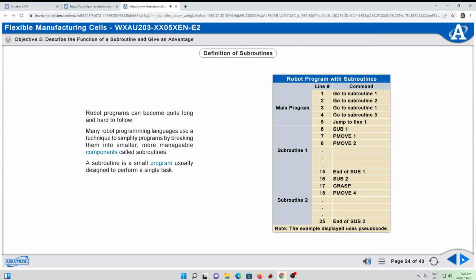Although the actual program may consist of hundreds of program lines, those lines can be grouped according to the tasks they perform. For example, each listing in this general sequence can be made into a subroutine which would contain all the program lines necessary to perform that task. Notice that some tasks are being performed more than once. For example, Tool 1 is picked up several times.